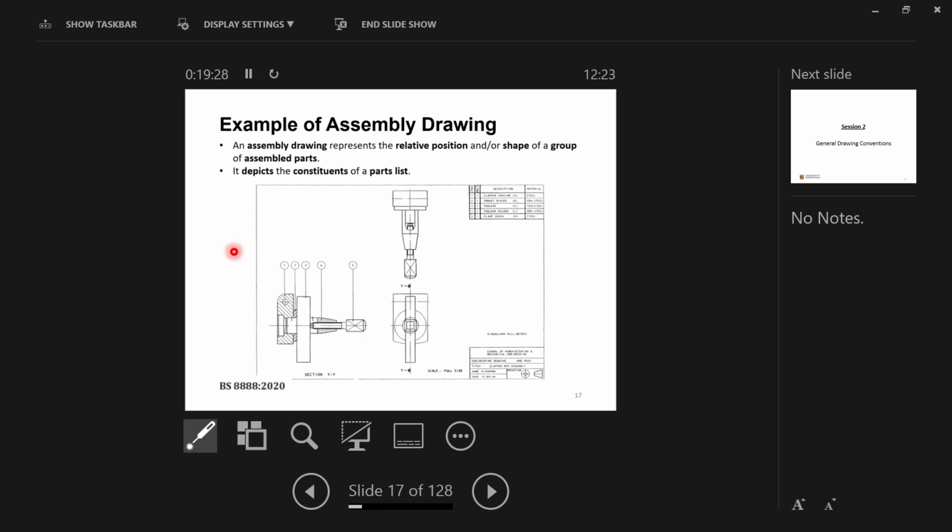So here is another example of an assembly drawing. You see here we have 1, 2, 3 views, and then we have some sections, and this section line here, YY. So we have a section YY. This is when you cut this part into 2 parts, so you can see from inside and reveal the details. We're going to talk about sections as well. And here it shows the title block. Some more details are written here. We are going to talk in detail about title blocks.